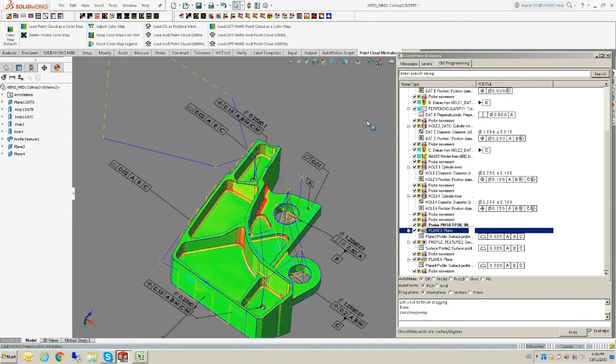What you're seeing now is a point cloud mapped onto the solid model showing deviations of the scanned part to the nominal CAD. This pretty picture provides a quick visual indication of what's going on with the part. Green is in tolerance, red and blue is out of tolerance. But generally in manufacturing, part approval or design corrective actions, more detailed information is required. So CheckMate can use our program as a soft gauge, and results data or substitute features are automatically extracted from this point cloud.